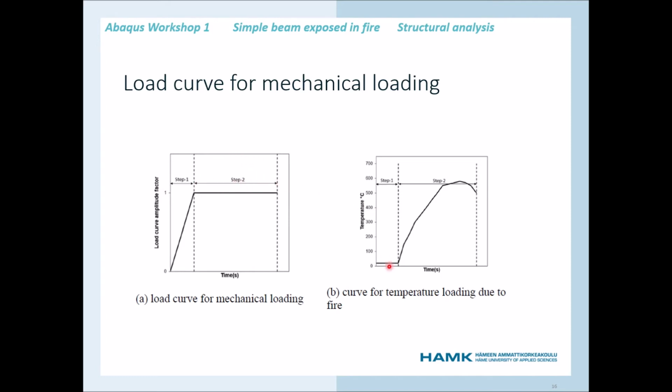And similarly, the temperature is defined initially in the first step, which is around 20 degrees Celsius, and after that in the second step, the temperature loading due to fire is defined. And now here in step 2, for the temperature loading due to fire, we obtain this curve from the previous thermal analysis.